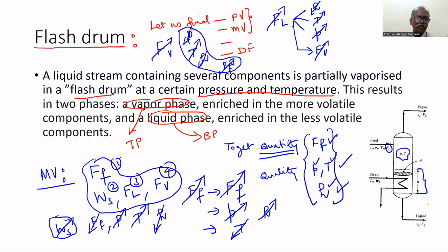That's why we have to select which manipulated variable has to be used for which process variable. There are four process variables, four manipulated variables. All the four are measurable. What are the possible combinations? 4 factorial possible combinations, that is equal to 24 possible ways we can combine the manipulated variables and the process variables. Out of these 24 possible combinations, we have to select only one.